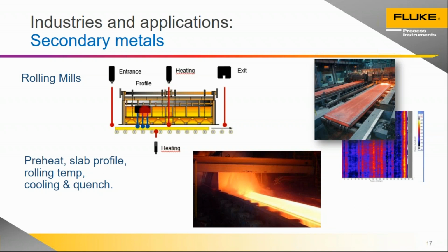Generally, this measurement of the soaking material is done through thermocouples that are placed inside that reheat oven or reheat furnace. But you can use pyrometers in that application, and one of the advantages there is you could really get the temperature of the actual material, not just the surrounding oven, and make sure that you truly have the temperature that you think you have.